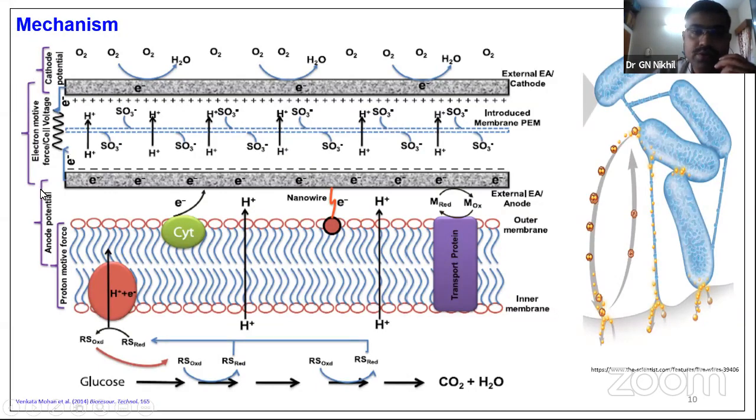So basically, you have these two electrodes, anode and cathode, and the basis for differentiating anode and cathode is the electrode potentials. Basically, every material has its own potential as long as it is conductive in nature. Based on the electrochemical potential series, every material has its own potential. When this material is immersed in a solution, its electrochemical potential varies. Similarly, when this electrode is put in a different solution or condition, its behavior, according to the electrochemical series, varies. So what decides anode and cathode depends on the potential.